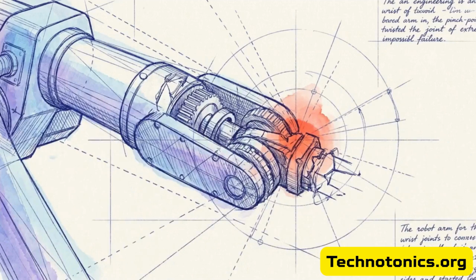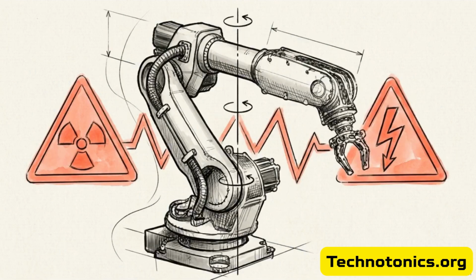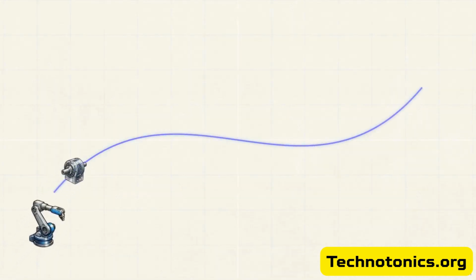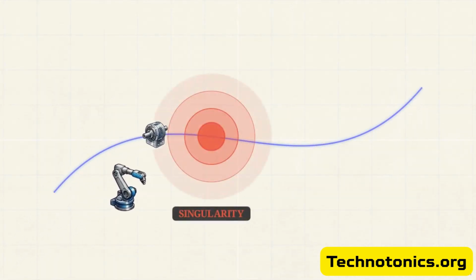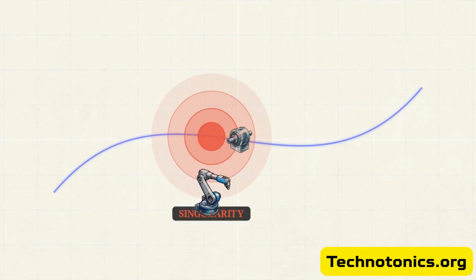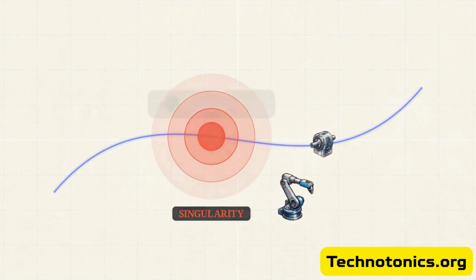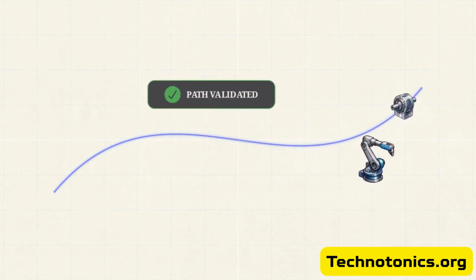The primary obstacle here is a singularity, a specific configuration where the robot's joints align in a way that mathematically paralyzes its movement or forces an erratic, unpredictable swing. To counter this, RoboDK actively analyzes the kinematics and automatically adjusts wrist configurations mid-motion, ensuring the trajectory remains predictable as it bypasses those dead zones.